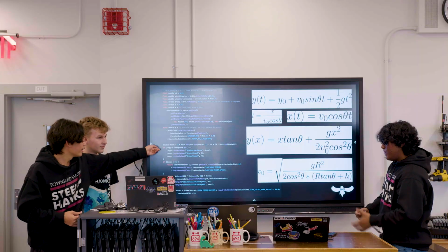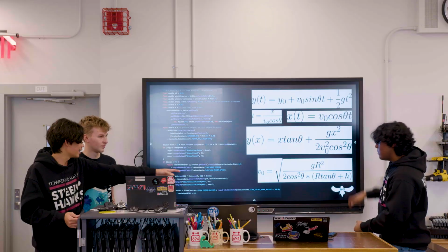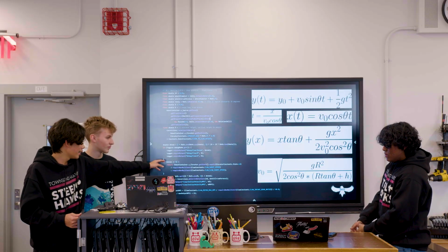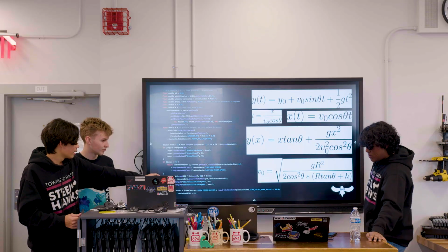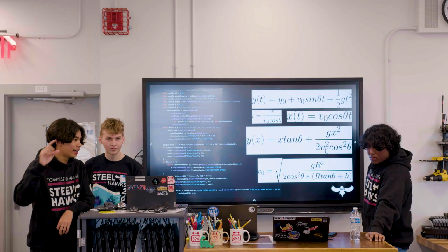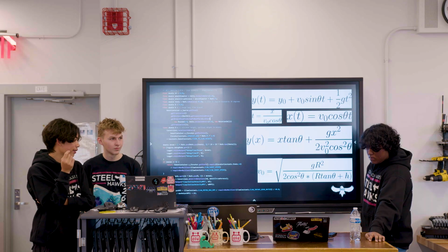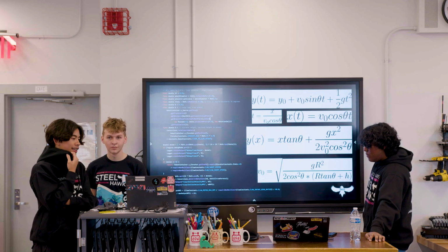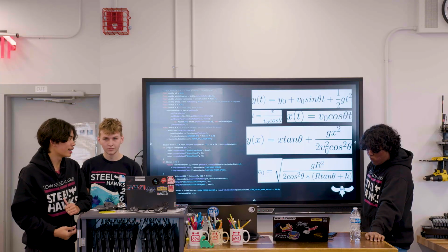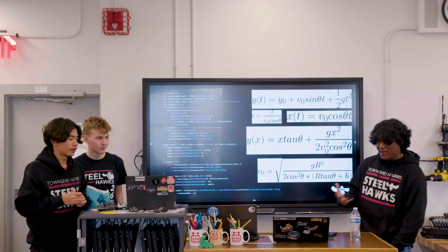So now we have this variable called denominator, which is, like the name suggests, literally just our denominator. We have this check, where if our denominator is less than 0, we're going to resort back to our initial shooting speeds for when the robot is flush to the reef, right? And obviously we need that because in the case that the denominator is 0, you're going to get a divide by 0 error. And also, you don't want a negative velocity because you don't want to shoot back inside your shooter.